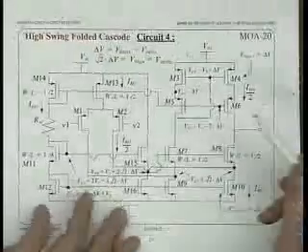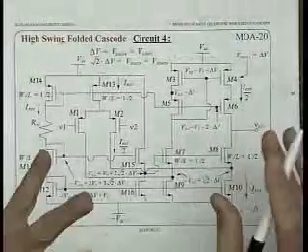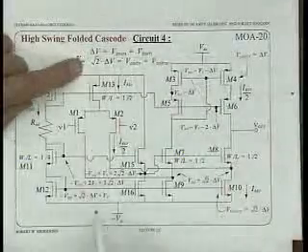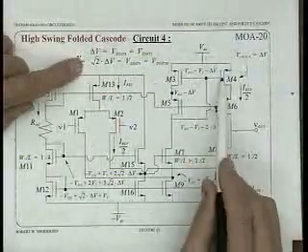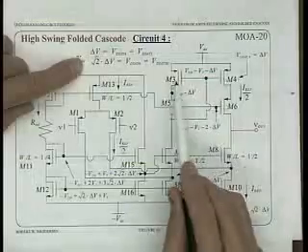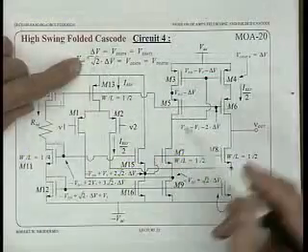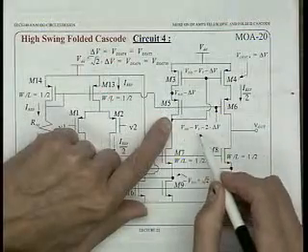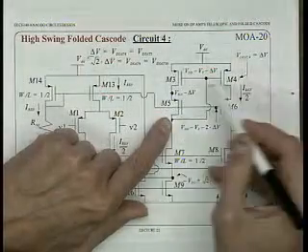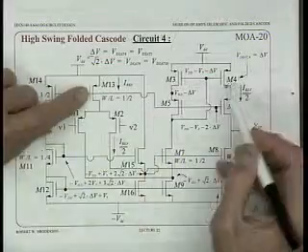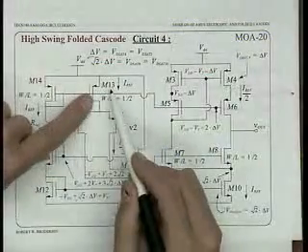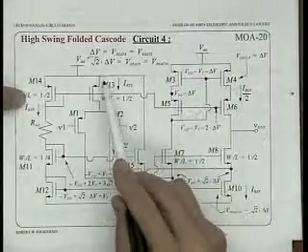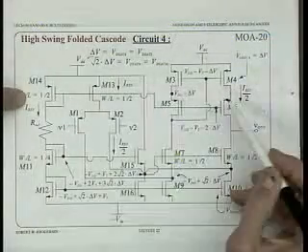And you can sort of see I did it here. Delta V's are sort of a nominal VDSAT, right? So delta V equals VDSAT of 4. These two, let's call that VDSAT, delta V of 4 and 3. So I call that delta V. If you look at the voltage at this node right here, it's VDD minus VT minus 2 of these delta V's, which are the VDSATs of 3 and 4. VDSAT of transistor 13, for example, is equal to 2 of these VDSATs, right? Okay.